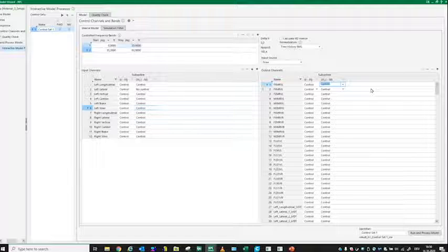But of course, you can still see in model some channels which are on no control in certain areas here, but it is meant to have them in simulate just as control channels, as correlation channels, if they don't contribute to the drive. So if it's really just a monitoring channel which is not changing or contributing to your iteration process, this one will be set as a correlation channel in simulate, and depending on the settings you made here, these channels will still show up as correlation channels as you are used to. Hope this answers the question.